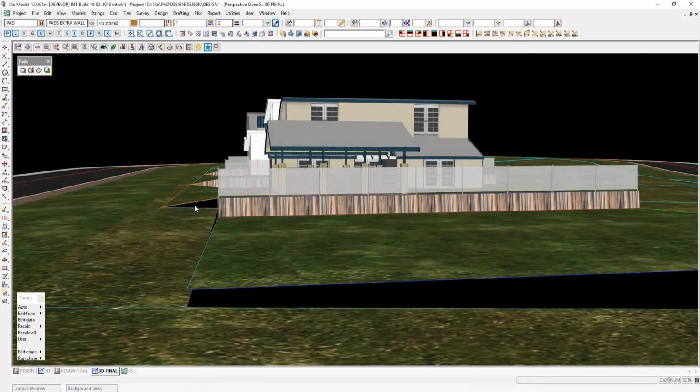So I've got a model for this little triangle that represents the extension of the wall, and then a model for the footpath transition. So we'll just do the wall first. I'll simply go into the create polygon by freehand, turn my line snap off, and I can snap onto the top of the other pad, the bottom of the pad I just created, and it creates that little triangle for me. So again, if I now run that pad, it then is part of the triangulation, so obviously it then updates, and that's the transition of the wall down to nothing.